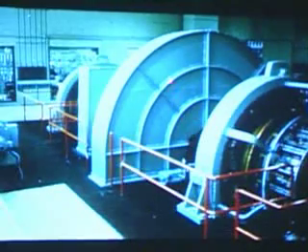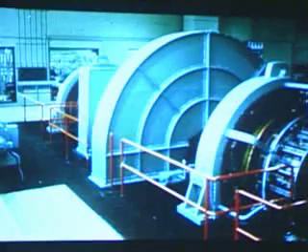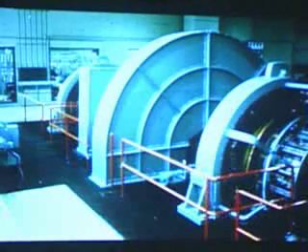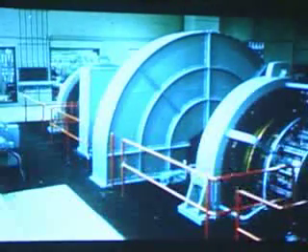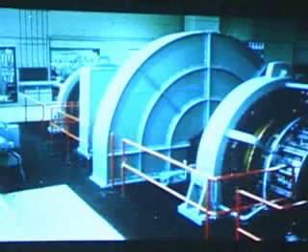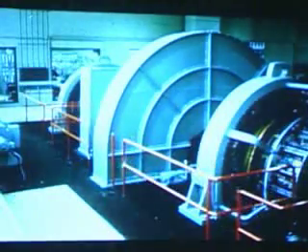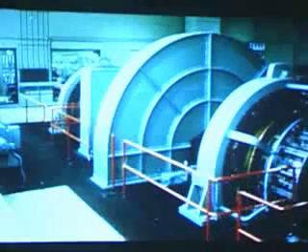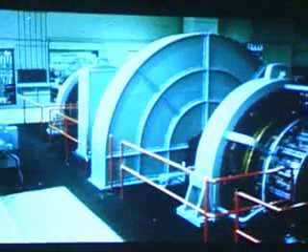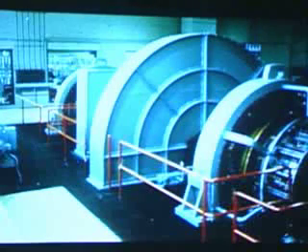What you see here are these flywheels at the magnet lab. These are the wheels that have a mass of 85 tons and that have a radius of 2.5 meters. An incredible, ingenious device, and you can store in there 200 million joules, and you can dump it into magnetic energy and in 5 seconds dump it back into kinetic energy of rotation. This is an amazing accomplishment, by the way.